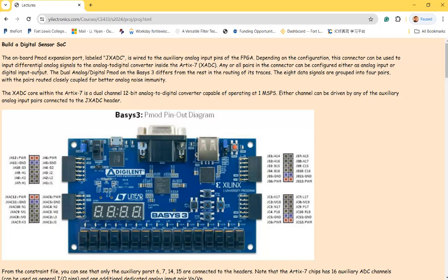Okay, so the photodiode receives light, like the camera has little photodiodes in each pixel, right? It receives the light intensity or light signal and converts the light into photocurrent. The photocurrent runs through a resistor and the current is converted to voltage. The voltage is amplified and then digitized by ADCs, analog-to-digital converters, and then you get a digital signal. It could be 8-bit, 10-bit, 12 bits, depending on the resolution of the ADC. That's the workflow. Then you get digital data in parallel.